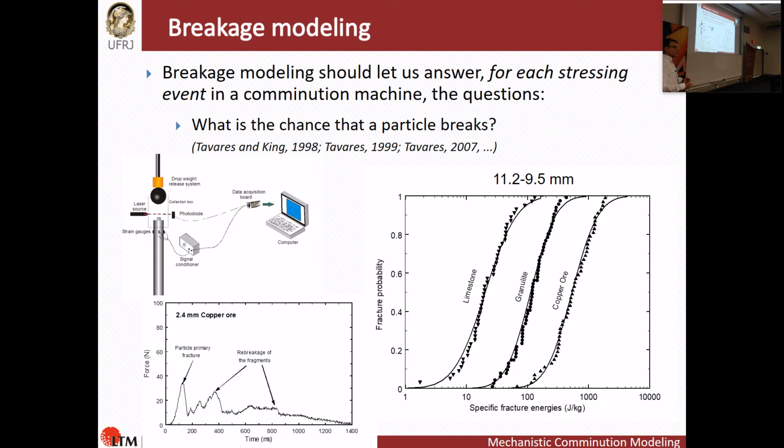We have to understand variability. Just describing things as averages, we get away with a lot of the time. We know that power models, power-law energy-size reduction relationships, cover a lot. But if you want to know the details, we have to account for this variability. We're not talking about experimental error here. It's actually natural material variability because of variability in cracks and everything. So the nice idea is that you can discriminate between materials. There is variability, but there's still clearly a fingerprint that you can measure.